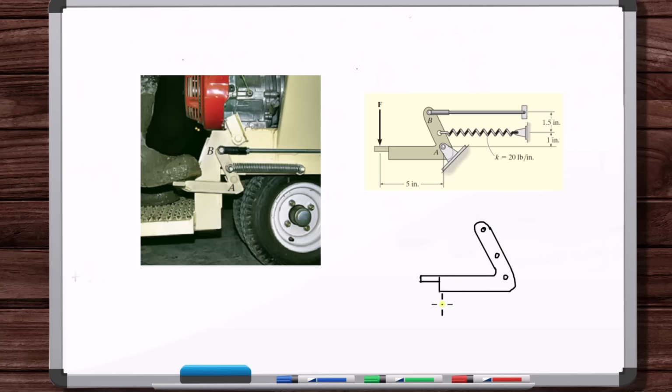Okay, so we know all of the contact points, so we know where there's forces. What we need to do is apply all of the force information. There's going to be force information that we know and force information that we don't know. Knowns and unknowns. You'll see people talk about unknown forces and known forces, but you might know a force magnitude, but you don't know its direction, for example. So I'm just going to say force information that you know and that you don't know. What type of information about a force is there for you to know or not know? You have the force magnitude, the force direction, and the force location, the force position, right? Maybe this force is here instead of here.